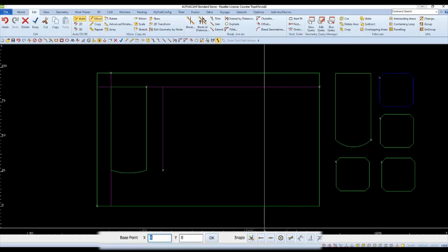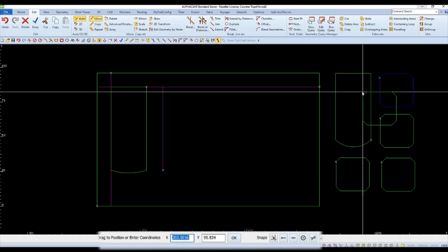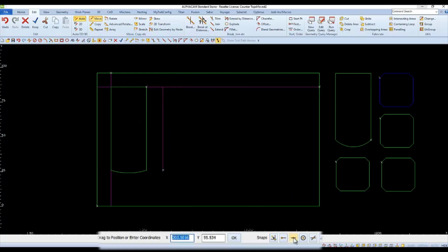So we can choose Move, and then select the next part to be moved, follow through the finish, and then we'll grab onto it by the intersection of the two flat lines. And I'll set this point down on the end point of the new line that we just offset. Repeat this process for the rest of our parts.